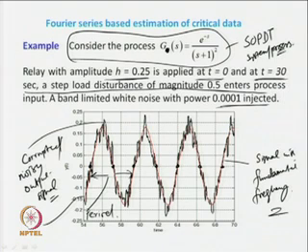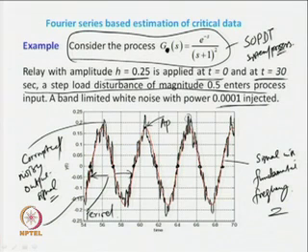And now, similarly, if I look at the plot in red, the peak amplitude is unique. Unlike this plot, which one is to be taken as the peak amplitude? If you take this one, this might be the contribution from the PSD of the noise, power spectral density, or the random values we have added. So, the correct value for the peak amplitude must be obtained from this plot in red.